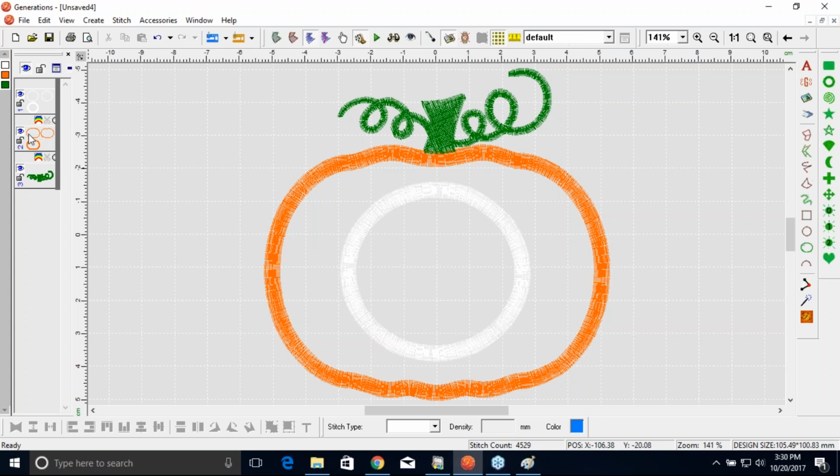And when you press start again, it'll then do the tack down stitch. The tack down stitch will hold down the fabric so that you can cut the fabric after it's secured onto the garment or onto whatever you're stitching on. So the second step, it'll do the tack down and it'll stop again. And at that point, you can take your scissors and go ahead and cut around the fabric. Once that's all done, you press start again, and it will do finally the cover stitch. So again, it's breaking it up into that 3-step process.